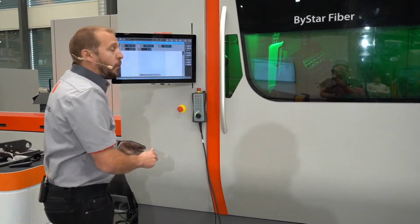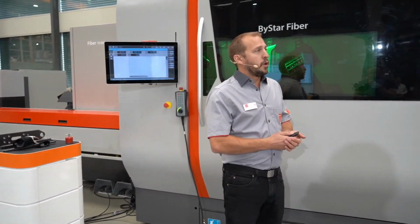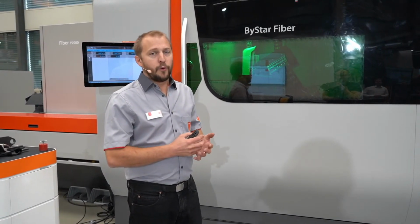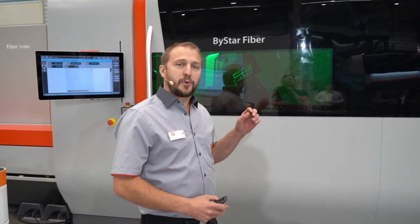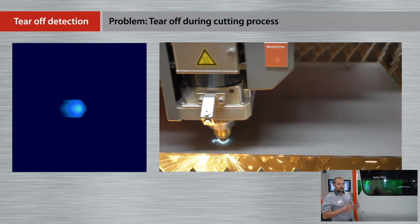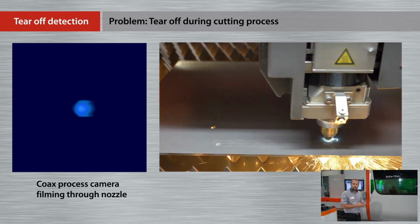As Michael just said before, we have a new option that is called parameter tuning. So the parameter tuning is a tool that we are developing for employees with little experience or no experience for unknown material. The only thing the operator does is pressing the start button. After that, everything is happening fully automatically, which means we are cutting 5 parts with 5 different parameters. We're labeling the part, so you have a number on it.